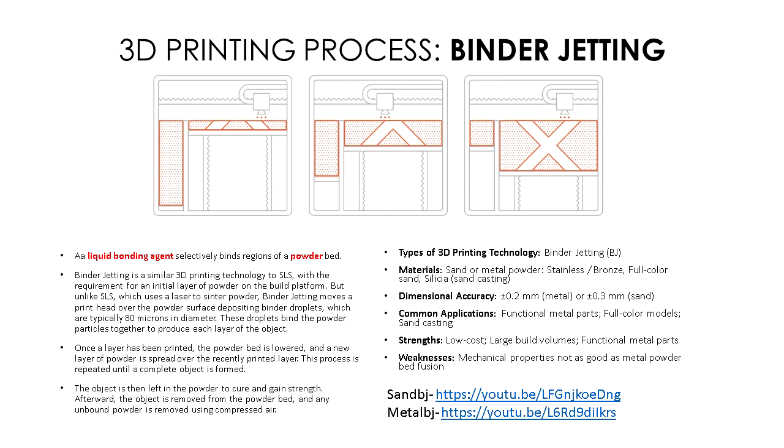Binder jetting, how it looks, means they have two containers of powder, with a mix of, I think last time, cornstarch and their secret ingredient, and then they have a liquid bonding glue. So they spray glue, like normal ink, on this flat bed of powder, and it will bind together. So the technology is binder jetting and metal jetting. So now we have metal. Last time we only had cornstarch-based powder.